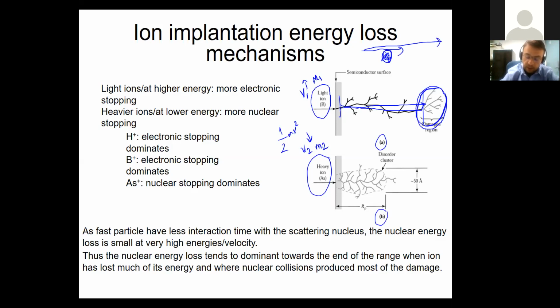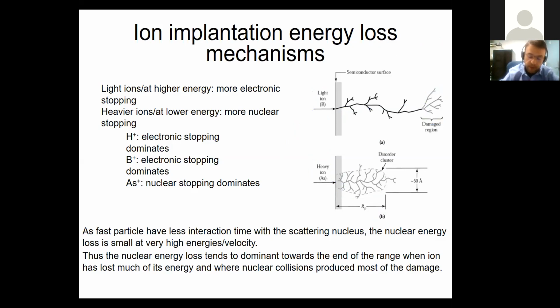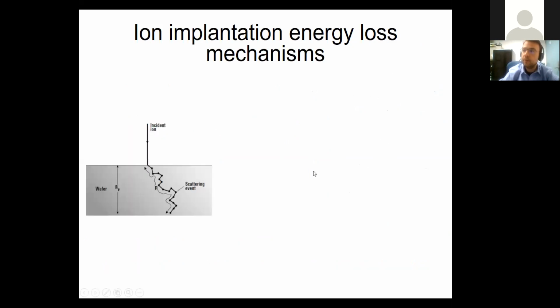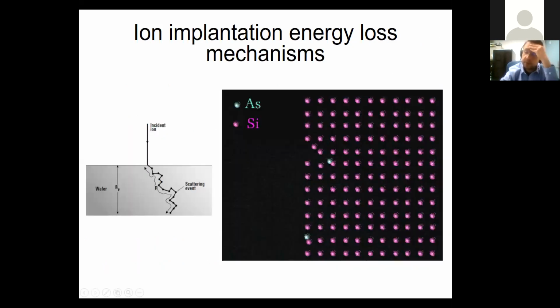As for the arsenic, at its starting point it doesn't have that kind of a velocity, and it will start interrupting the crystal structure already initially. I'll show you, I hope the time will permit, in SRIM, the simulation tool that we use. But arsenic is now penetrating in, as you can see, and it's dislocating the silicon atom. We have seen these defects. We didn't see ion implantation, but we have seen these defects getting formed. These were the interstitial silicon atoms that were created, and if the arsenic was stopped, that would be a foreign atom point defect structure